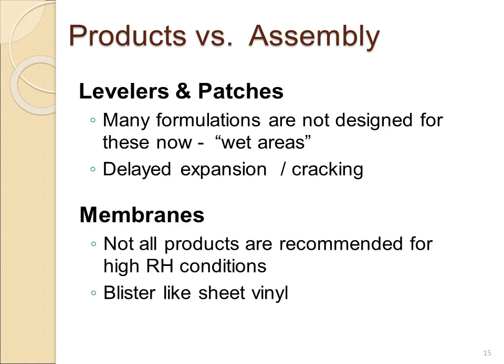When we think about other products that are used in the assembly, such as levelers and patches, if you read the data sheets for most levelers and most patches, they're not designed for wet areas. They have materials in them, formulations where you can get delayed expansion. And that's a nightmare for a project where now you have leveler that literally is pulling itself off of the slab and cracking.